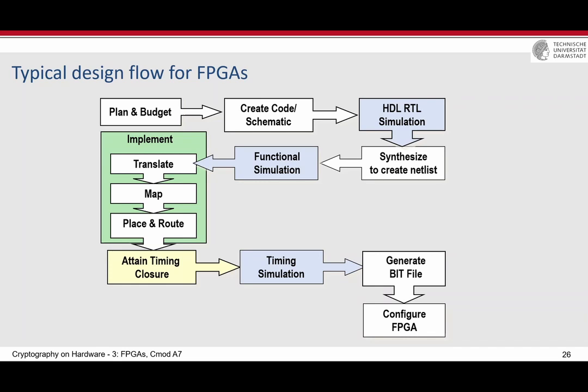In ASIC, it doesn't matter. It matters a bit, but it's just a wire, and the delay of the wire is much shorter than the delay of active elements like switch boxes. And then the development tools, for example, of Xilinx or other FPGA vendors, try, of course, to minimize this and do good placement and routing to meet the timing constraint that you give.